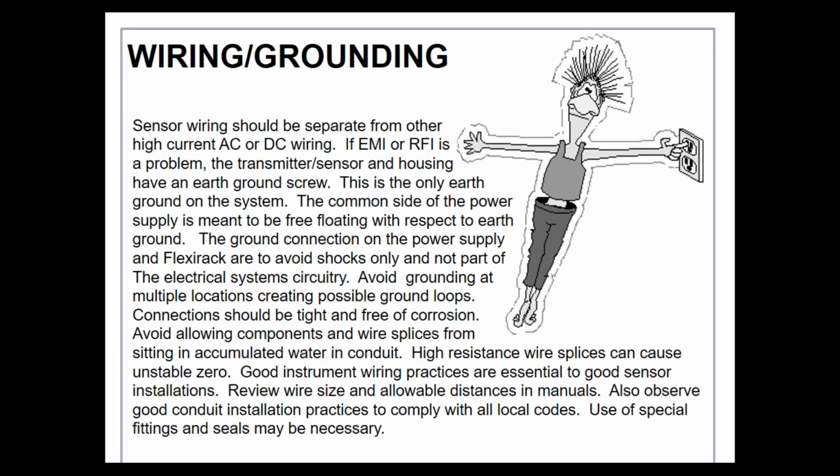One of the biggest issues that I've seen over the years is improper wiring and grounding. Gas detection is very, very sensitive. If you think of what is going on with a gas detector, it's seeing a very, very small signal.